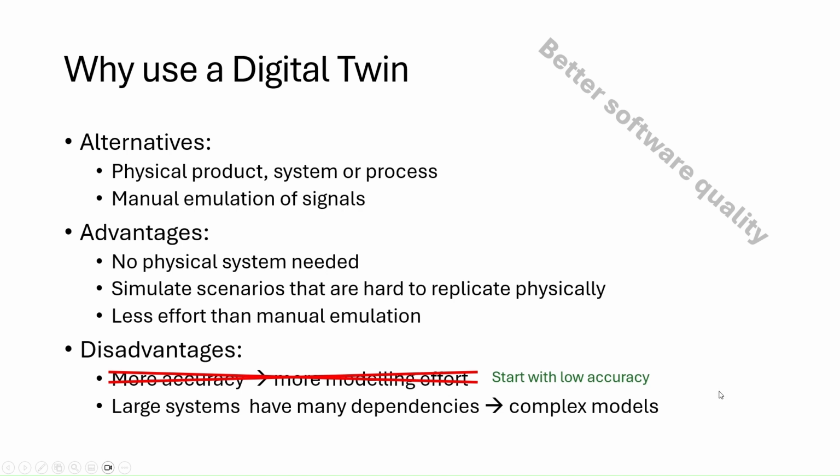So with the flow, as I mentioned before in the previous chapter, you can just use a proportional signal for the flow that is being created according to the pump frequency. So if the pump frequency increases, for example, you will get a higher flow, and that's just a proportional effect. And that's actually just great to test some basics of the control logic.